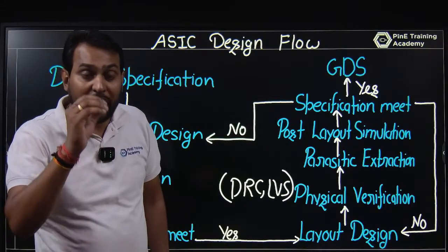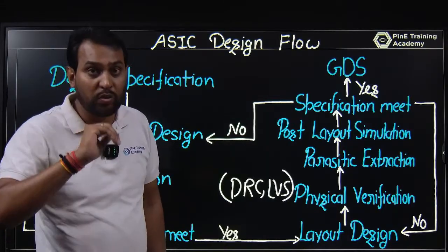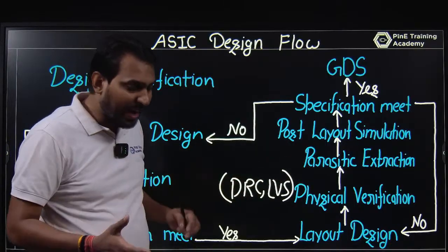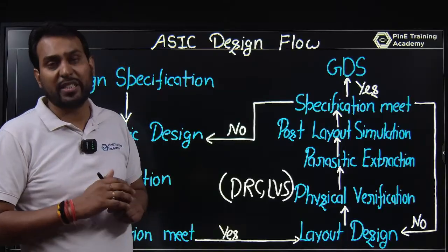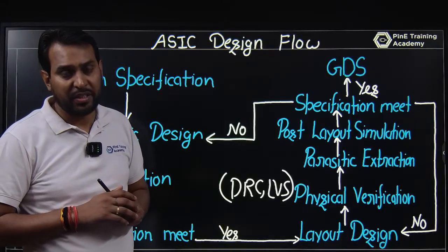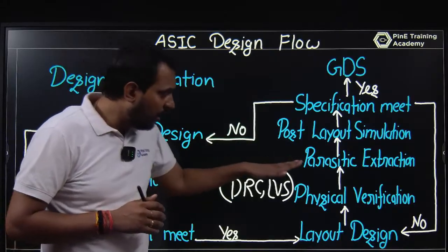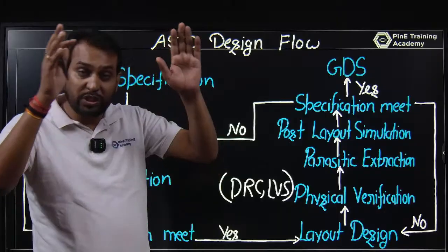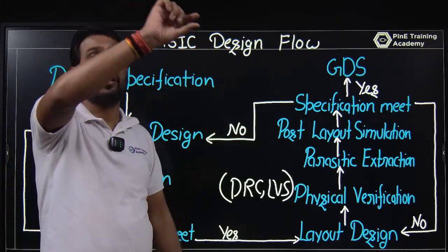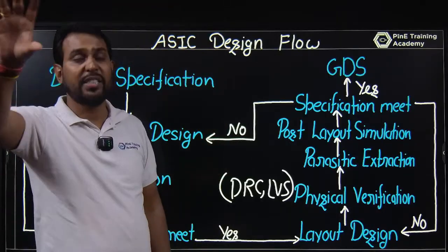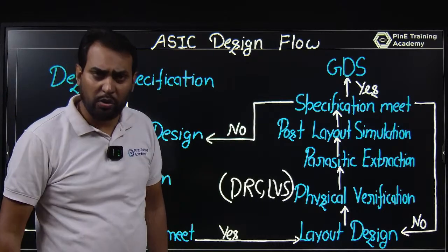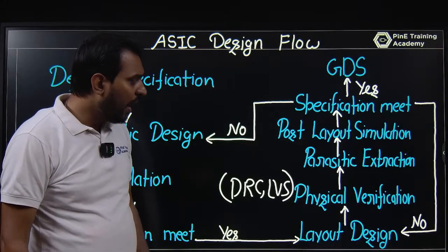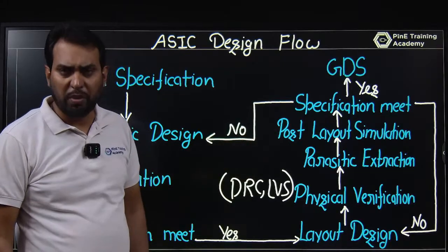So how can you understand what the value will be? By the help of parasitic extraction. In Cadence you will use QRC, that is Quantus RC extraction. So you will go for parasitic extraction. Here you have a set of values: this coordinate has this resistor, this coordinate has this capacitor, and this amount of value is given in the CIW. And then you go for post layout simulation.